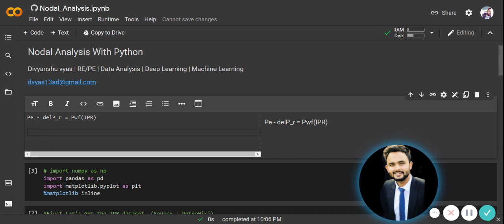For those who already know about IPR and TPR, they can just skip on to the later section of this video where I talk about basic Python code. But currently I'm talking for those who are new to this concept. So PE minus delta P of the reservoir gives you the PWF IPR as we have traveled from the external point of the reservoir towards the wellbore. This is the equation for IPR pressure differentials.